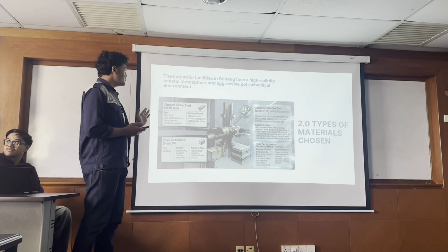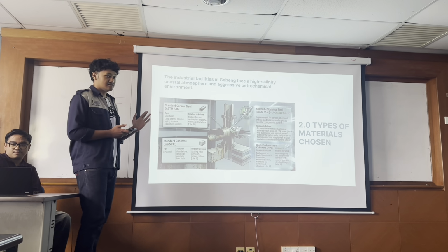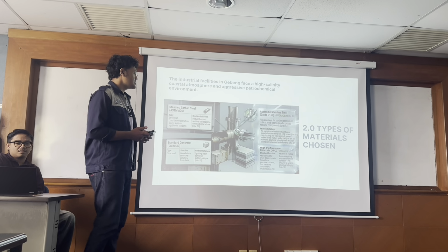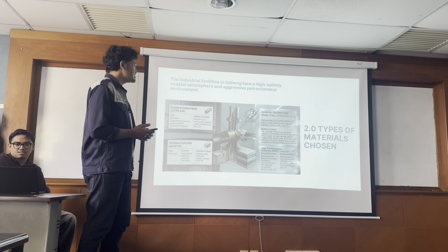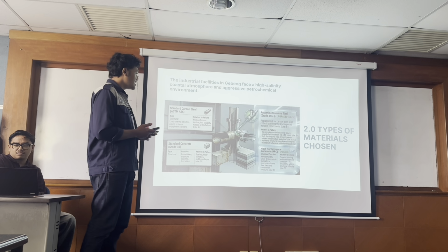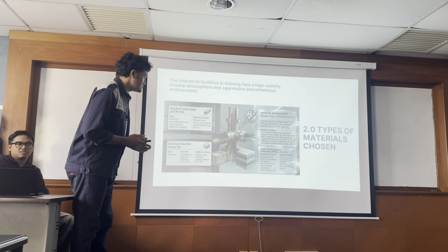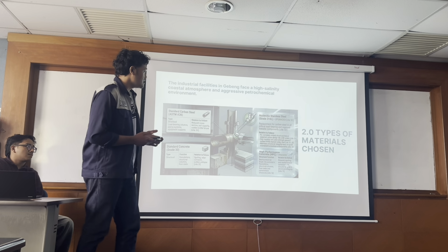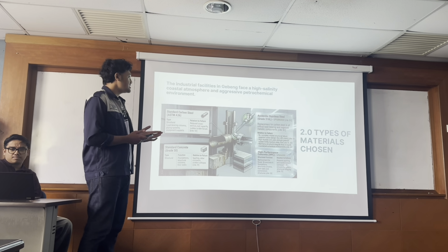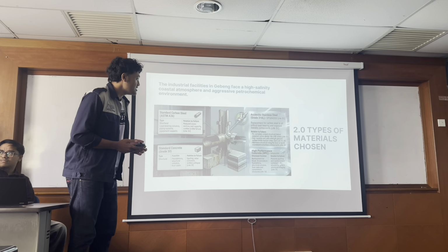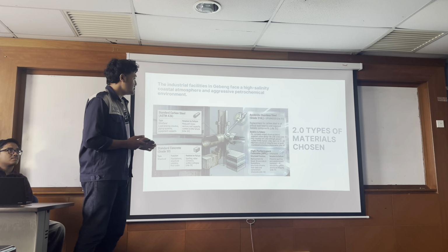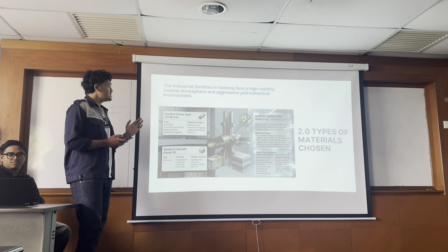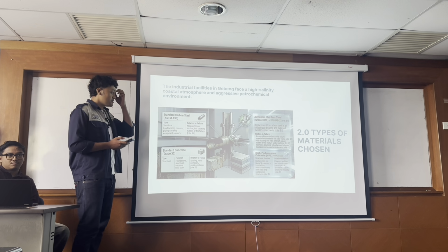The improvement that we get from the upgraded material is that no corrosion related structure failure is expected within design life, and also high ductility and yield strength prevent sudden brittle fracture under heavy load. It also maintains structural integrity even in the harsh coastal and petrochemical environment, which is the Gebeng industrial main industry.